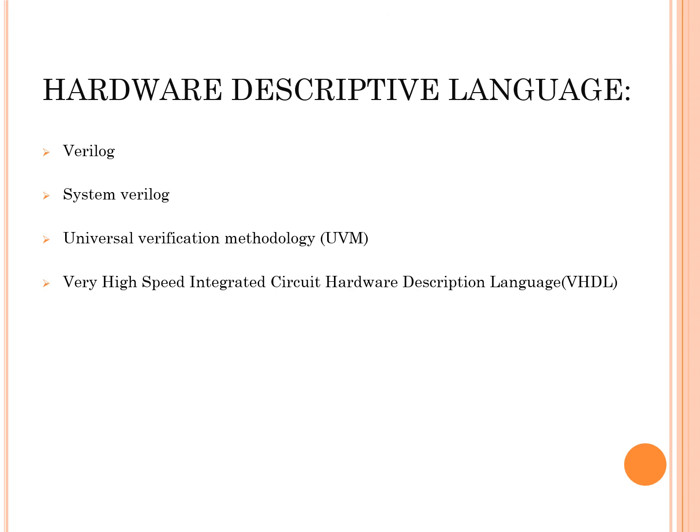For advanced verification, there is UVM, the Universal Verification Methodology, perfect for complex chip verification and emulation. Another important one is VHDL. It's important in defense and aerospace industries, used to model and simulate digital systems, especially for FPGA and ASIC designs. Basically, you describe how your circuit should behave using code, and then the synthesis tool converts the description into the actual logic gates and hardware. Pretty cool, right?